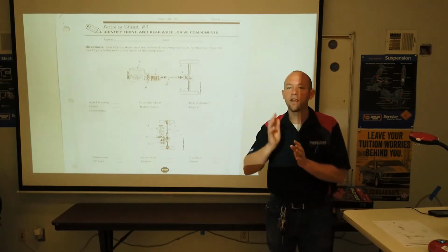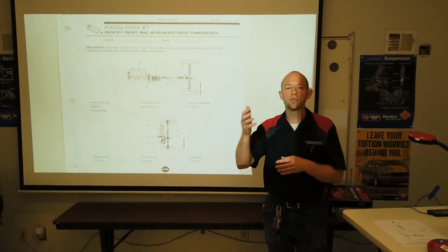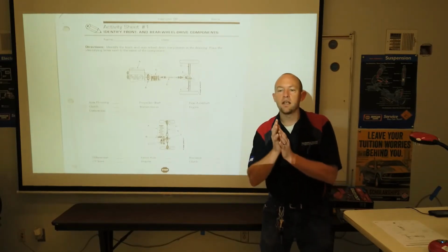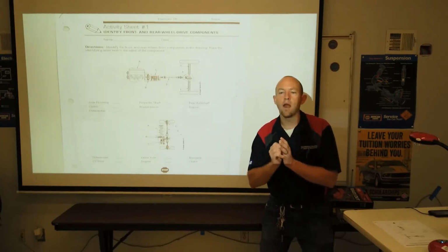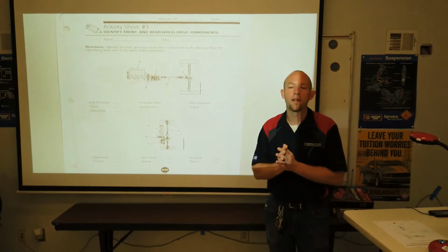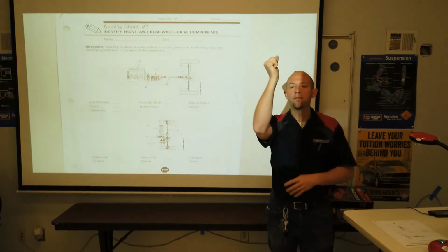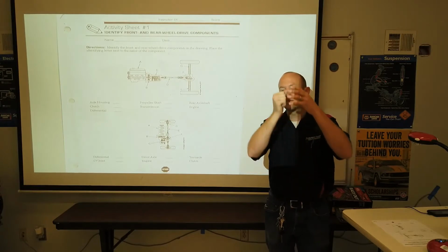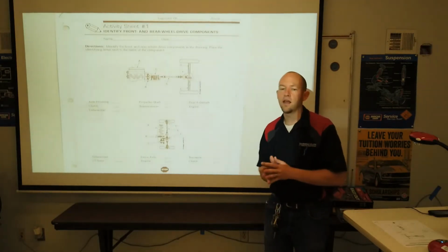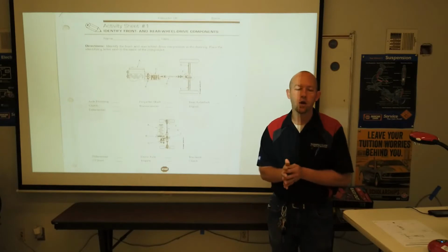And as the exhaust gases are leaving, the property of inertia helps us, that an object in motion wants to stay in motion. The intake gases and air-fuel mixture, since it was not moving, would want to stay at rest. So as the exhaust valve and the intake valve are open at the same time and those exhaust gases are flowing out of the exhaust valve, it helps to siphon and get the air-fuel mixture moving past that open intake valve. And then as the piston nears top dead center of the exhaust stroke, we're going to have our intake valve starting to open. As we come down our intake stroke, our exhaust valve will close. And then now that the intake gases are moving, they're going to be easier to keep moving because of the law of inertia. And then we end up filling the cylinder and have a 4-stroke cycle that starts all over again.